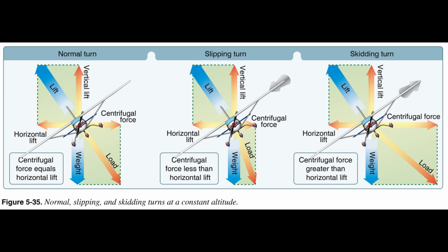For instance, at 400 miles per hour (mph), an aircraft must be banked approximately 44 degrees to execute a standard rate turn, 3 degrees per second. At this angle of bank, only about 79% of the lift of the aircraft comprises the vertical component of the lift. This causes a loss of altitude unless the AOA is increased sufficiently to compensate for the loss of vertical lift.